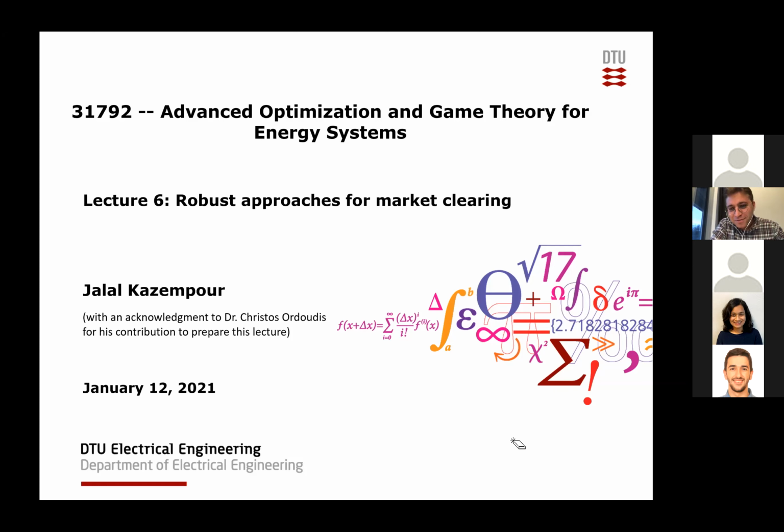But we always had a big, strong assumption that our 4 scenarios can adequately characterize the underlying set of the uncertainty. It means that the wind power uncertainty is characterized very well by 4 scenarios. We don't know if that assumption is correct or not. Specifically here, most likely it's a very strong assumption, and it impacts the results. If instead of 4 we go to, I don't know, 10 scenarios, most likely we will get a different solution.